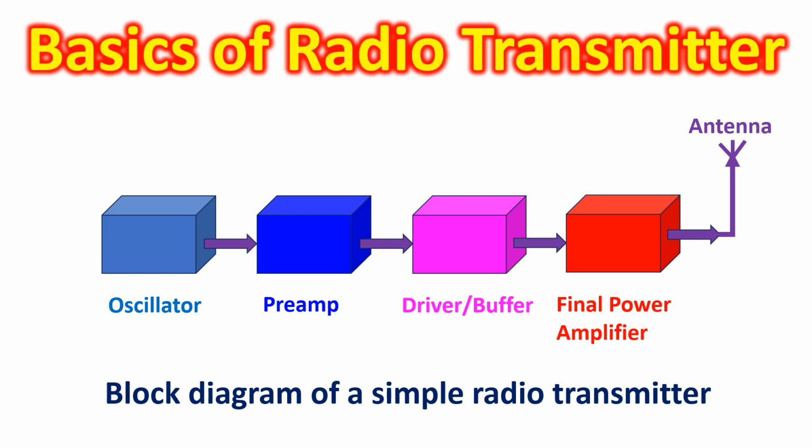Like many other radio amateurs in the yesteryears, I had also homebrewed a basic CW transmitter using BD139 transistor as the final RF amplifier, running about 5 watt, known as QRP transmitter. Initial part of the transmitter is the radio frequency generator, known as oscillator, which produces a high frequency oscillating current when you supply it with a direct current power supply.